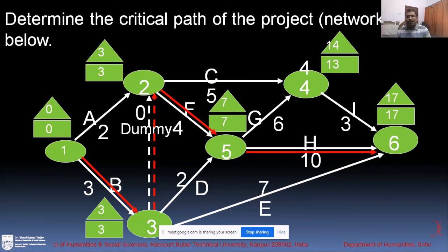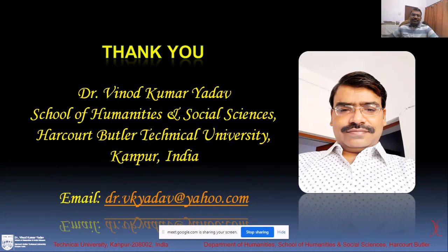There is no slack. In this one there is a slack, and that is why we excluded this activity. So this is not coming on the critical path, and since it is not on the critical path, it is a non-critical activity. So we just tried to look into